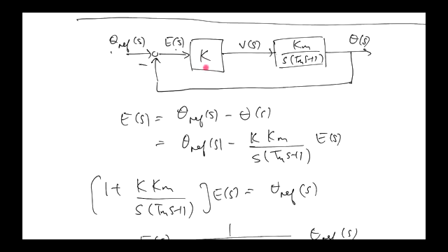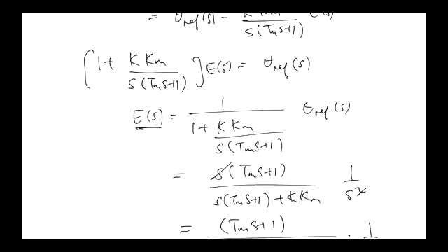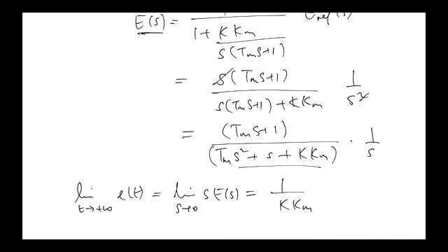We're just choosing the controller gain K. We always end up with a stable closed-loop system. We always end up with the error signal going to a constant value in steady state when the reference is a ramp, and we can make the error as small as we like by choosing K sufficiently large.